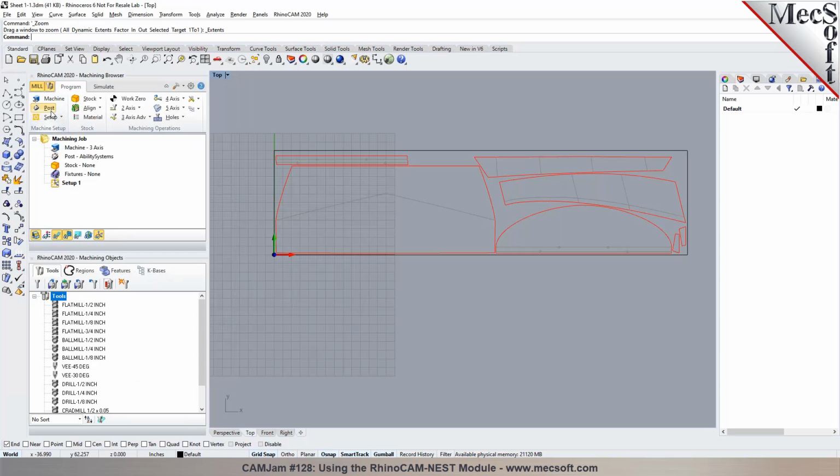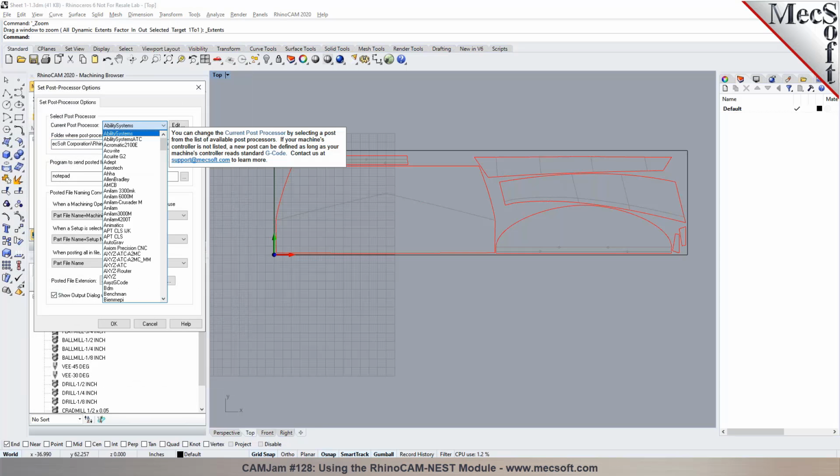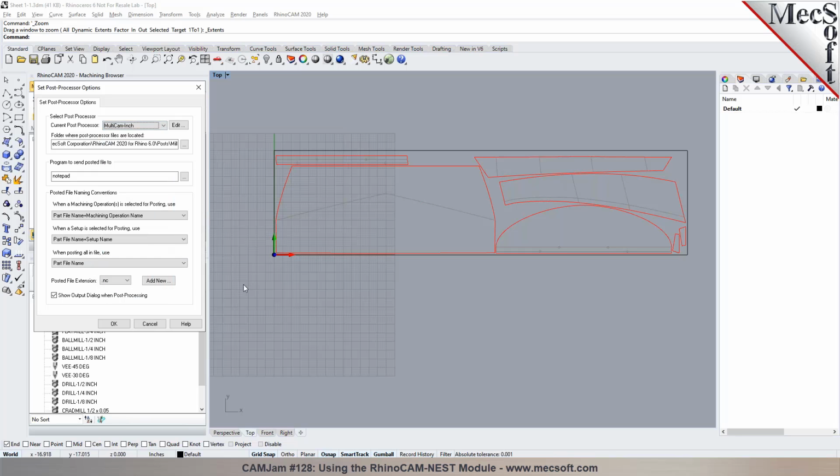The next step is to select the post processor. This depends on what machine tool you're planning to write the G-code output for. It's a multicam brand, so we do have posts for multicam in here. I will pick the multicam post right down the list. You can see there's some multicam. I'll pick the inch right here. Multicam can read .nc or .cnc file extensions, so I can type the extension as .cnc for multicam.